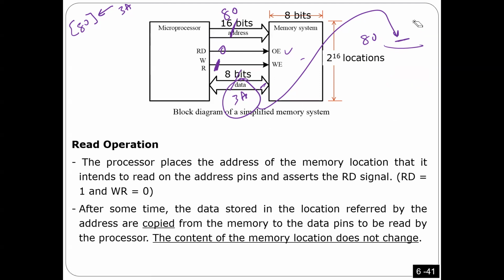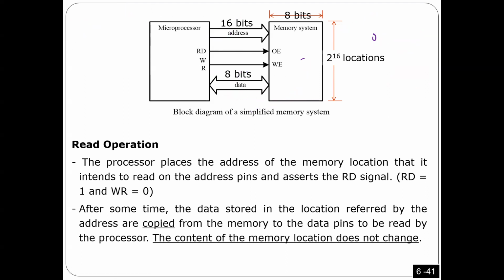Okay. There is a relation. I told you guys, usually this data is 8 bits because it is standard. You can design it to be whatever you want. You could store in every location 16 bits or 20 bits, it's up to you, but the standard is that in every location we store only one byte. However, there is a relation between how big the address is, how many bits we have in the address, and how many locations we have. How big is the memory?